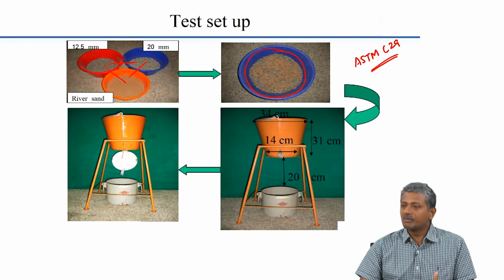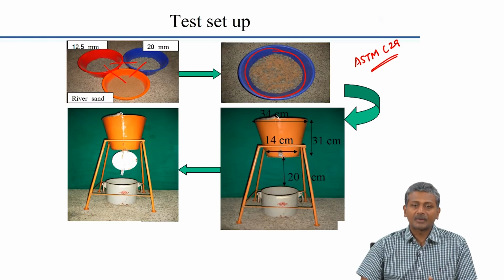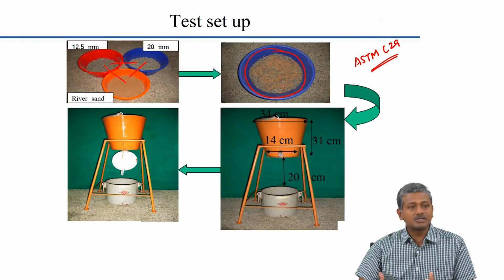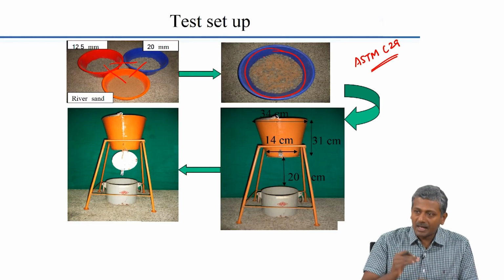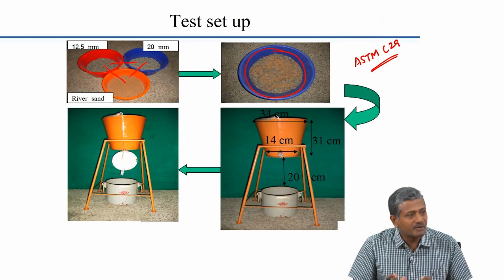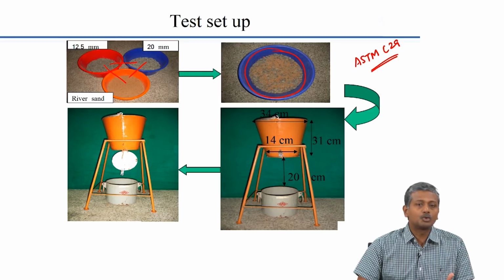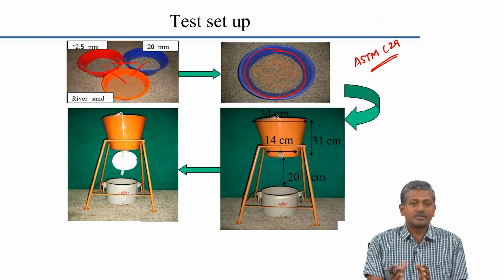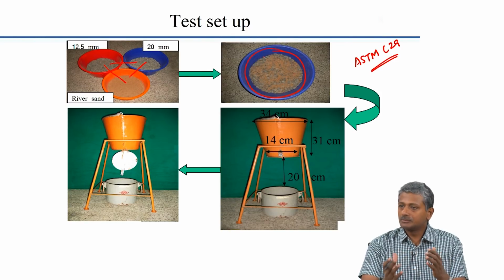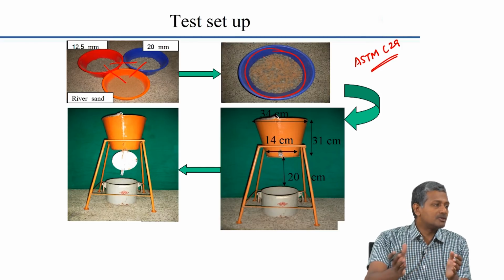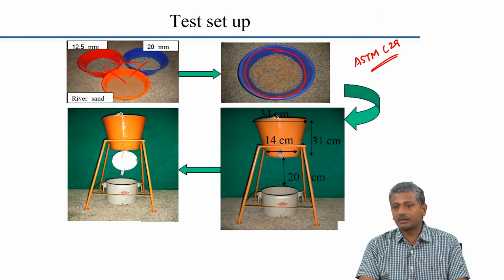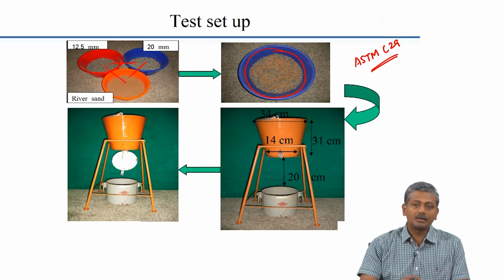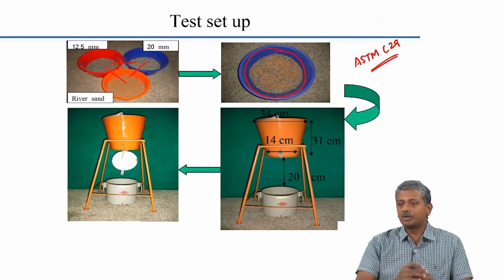Now, you know very well that when you are designing self-compactable mixtures, the flowability is very high. So, to avoid the dangers of segregation, you will proportion it in such a way that you already have a high enough fine aggregate content. You will never choose fine aggregate contents for SCC that are less than 45% of the total aggregate content. If you look at any design for SCC, the fine aggregate will be closer to 50% of the total aggregate content. So, you design your mixtures of the aggregate combinations with 50% fine aggregate and different percentage combinations of 12 mm and 20 mm coarse aggregate. And you do the same with 60% fine aggregate and then different proportions of coarse aggregate. Maybe you can also try 40. So, you have a number of different combinations which are possible.